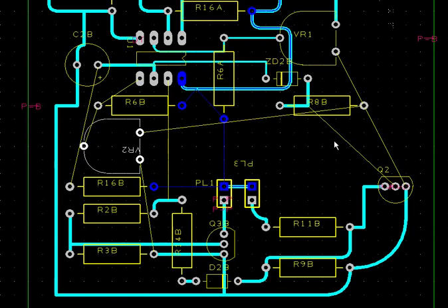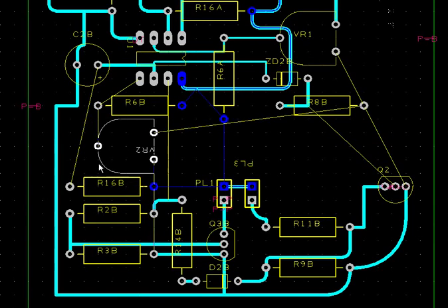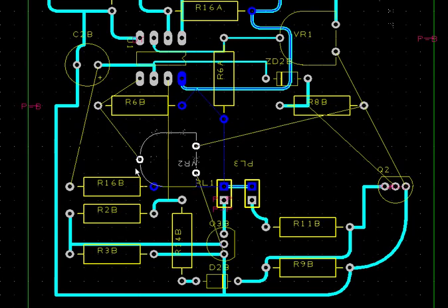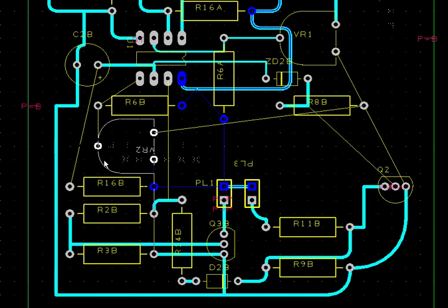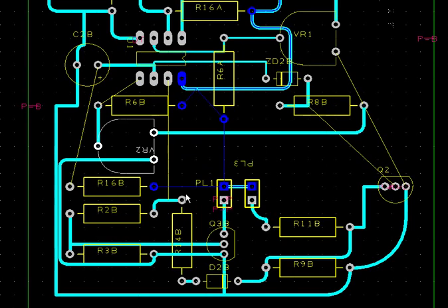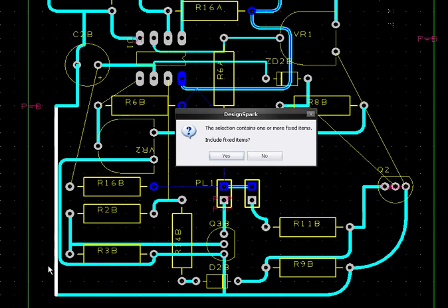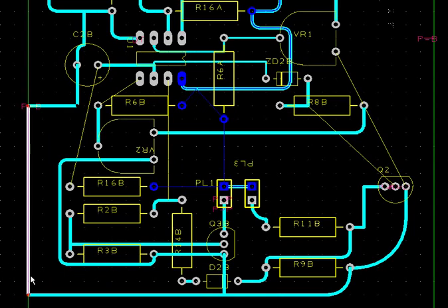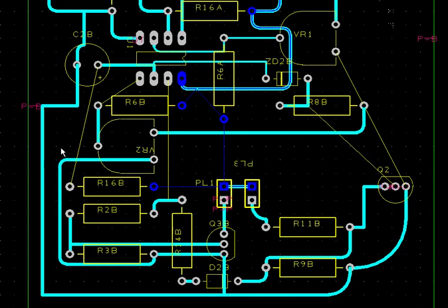So this is the whole point of designing the circuit board, to place the components in the best possible positions. For example, if I right click on here and choose auto route, it's auto routed a track. And this one has auto routed behind. Great, that's worked. Right, let's just move this track. You can move the tracks as well. Right, I've got the tracks in a better position now. That looks a bit better.